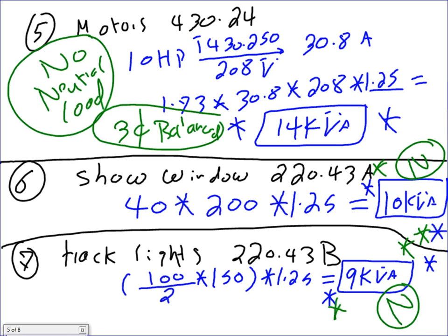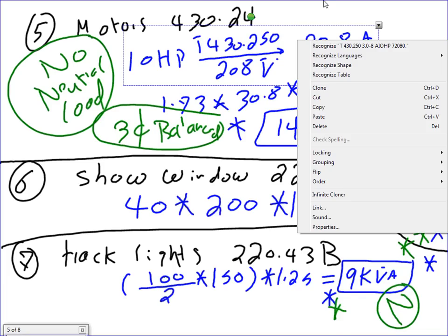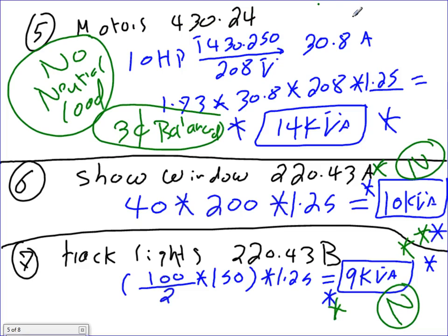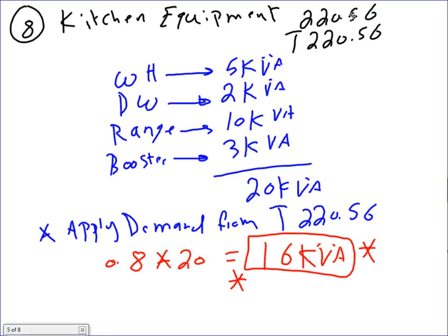Had this panel been 400 amp, I wouldn't even mess with it. Full neutral. All right. Next, kitchen equipment. You guys agree with me? These are 120, right? So I'm going to put my green star, and I'm going to put my neutral next to each one of them. I carried my neutral. Anything else left? So the kitchen equipment is going to be neutral.